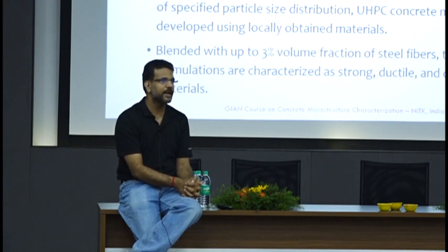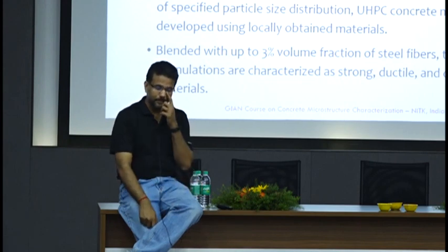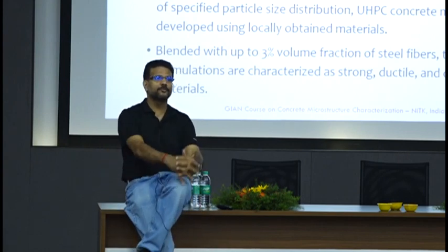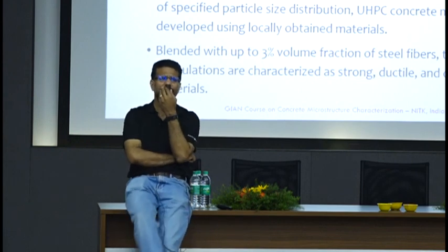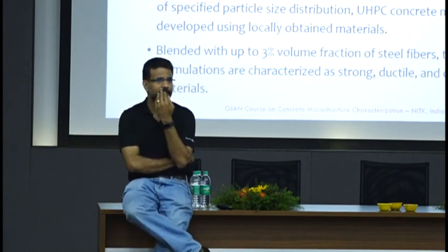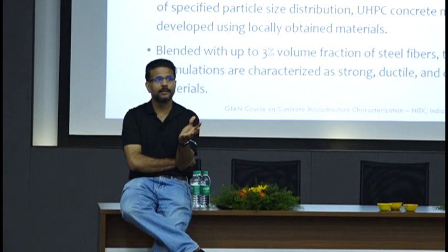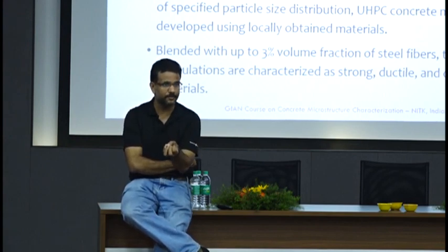Yeah. Your fly ash, metakaolin, yeah. Good question. So there are ways of doing it. Why would you want to do it? The question is, why would you want to find the contribution of fly ash towards strength? People have done it in the past. I think it's a waste of time to find the contribution of fly ash towards strength, metakaolin towards strength, silica fume towards strength. Because strength is an intrinsic property of how well you have packed your microstructure.